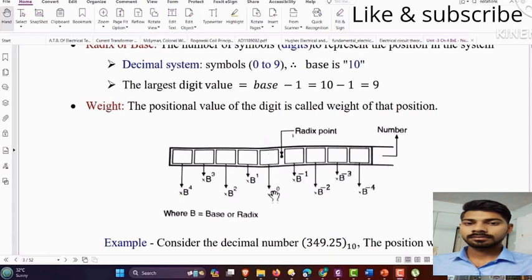And the position weight will be the power of the base starting from 0. So the power goes on increasing from 0 to n on left side for integer portion. If you see the fractional part, the right side of the radix point, then the position weight of the first position is given by b raised to minus 1, where b is the base again.